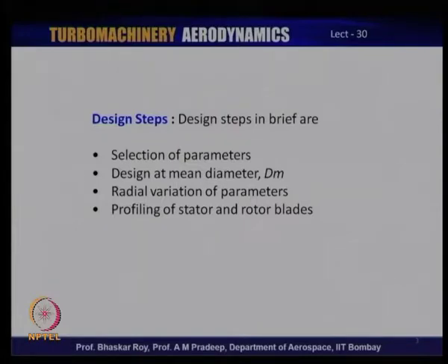Similar things need to be done for all the stages of a multi-stage axial flow turbine, and for all the stages then the profiling of the stator and rotor blades. That means, essentially, choice or selection or creation of the profiles of the individual blade sections would need to be undertaken. You may need to make something like 100 different profiles for all the stators and rotors to create a final multi-stage axial flow turbine.